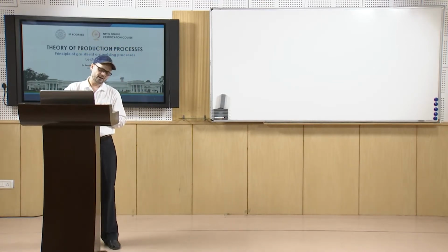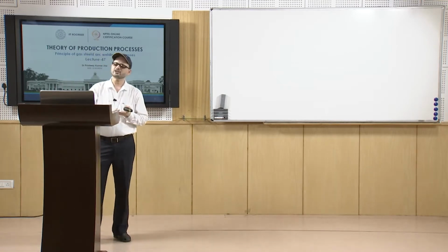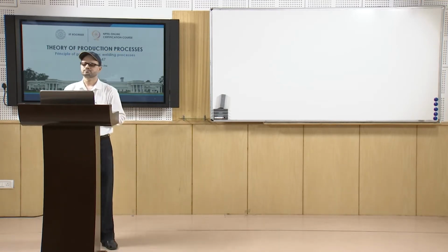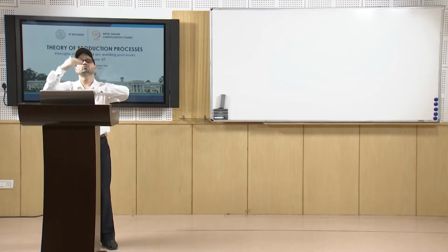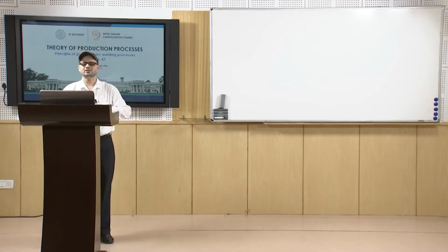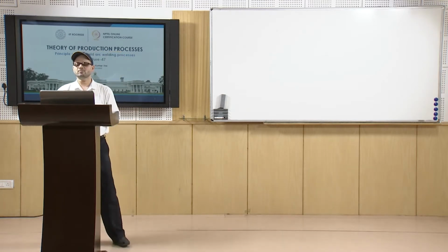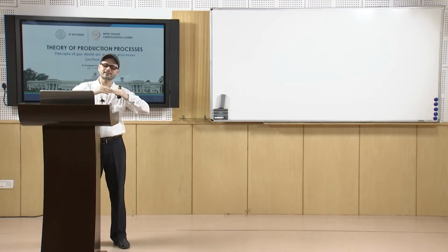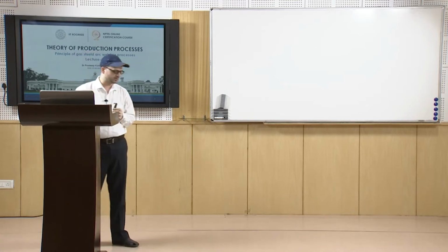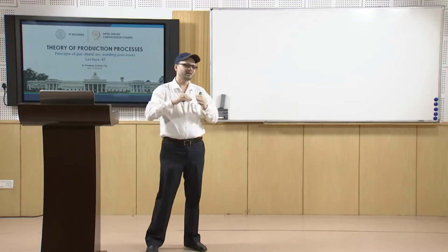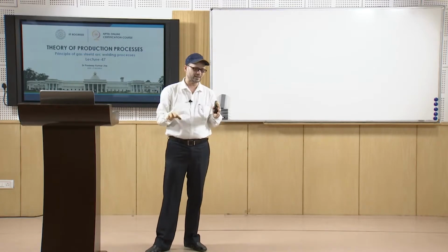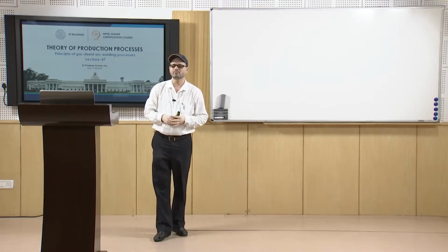So, electrons will be flowing from this base metal. The electrons which are leaving the base material also remove some of the oxides which are protecting the surface of the material, especially in the case of aluminum, as we know that aluminum has a protective layer of aluminum oxide.